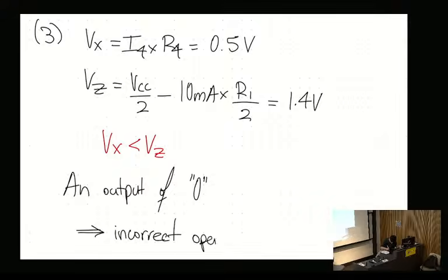Okay. Now investigating the short is exactly the same. You just analyze what happens to those voltage nodes and then you go from there. Failure analysis is always the same. You're just analyzing what the implication is on the operation of the circuit as a whole. So just do it fairly methodically.